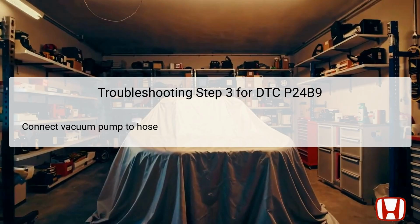This procedure enables pressure to be applied to the EVAP system, which is crucial for evaluating its performance. A vacuum pump is specifically used to generate a negative pressure. The gauge allows for an accurate measurement of the vacuum pressure created.